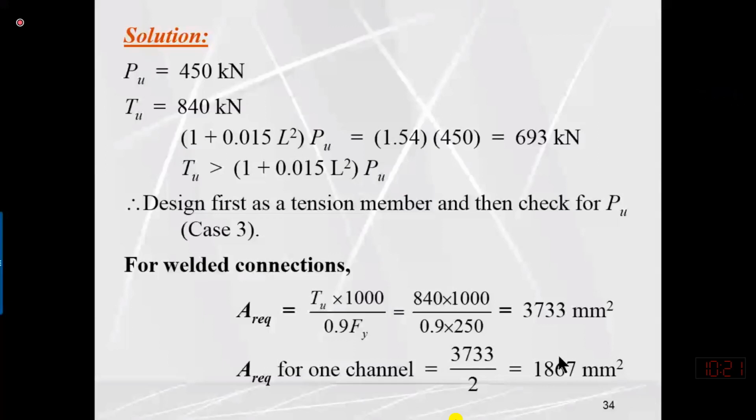If you open it, we will move backward from page 69. Try to filter out all sections whose area is equal to or a little bit more than 1867. On page number 69, all sections are quite heavy, and none of these sections is suitable on page 68.